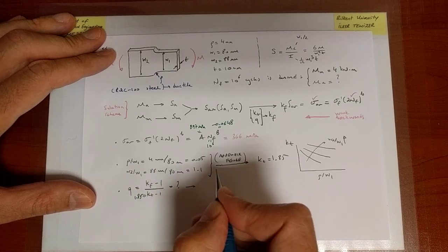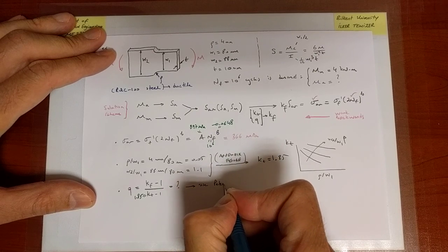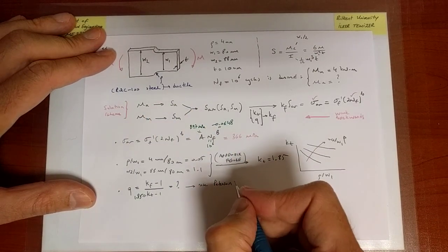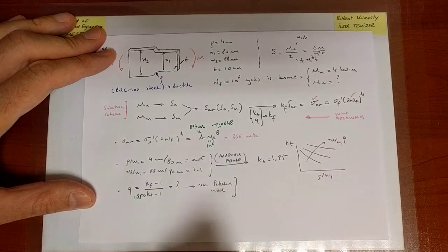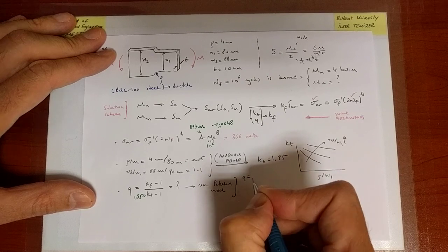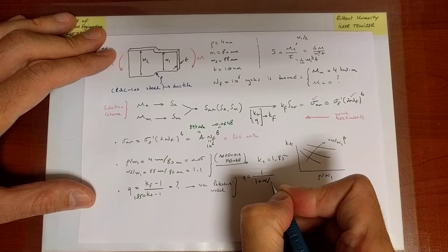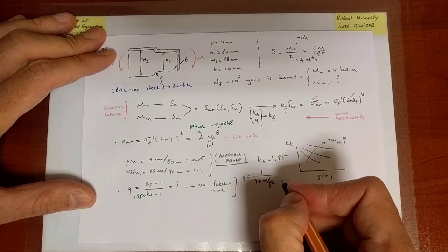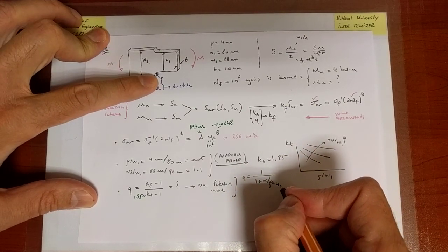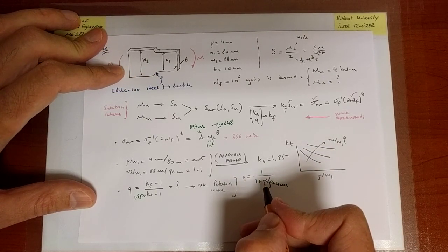So we're going to use here the Peterson model, which is good for steels. And the Peterson model, remember, says that Q is equal to, now this part one doesn't really have to memorize at all, or for that matter, it's hard to learn and make sense out of it, but that's the form where rho is the value of the notch radius, which is again 4 millimeters, and the alpha value is to be determined.